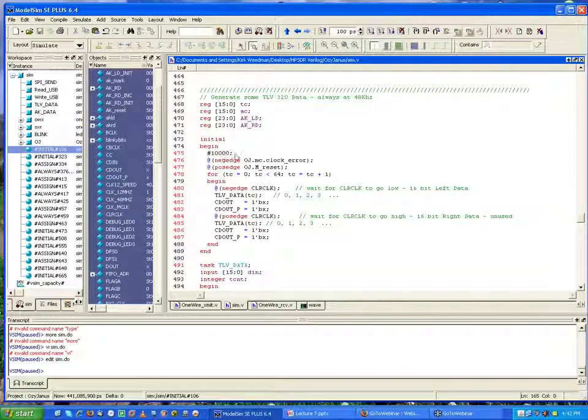So I said delay this amount of time, then I look for another particular signal. I wait for another reset signal that I'm looking for. And then I get to the real heart of what I want to send. I want to feed this stimulus of data into the part. So here I've said, okay, I'm going to do this 64 times. I'm going to send this particular data.